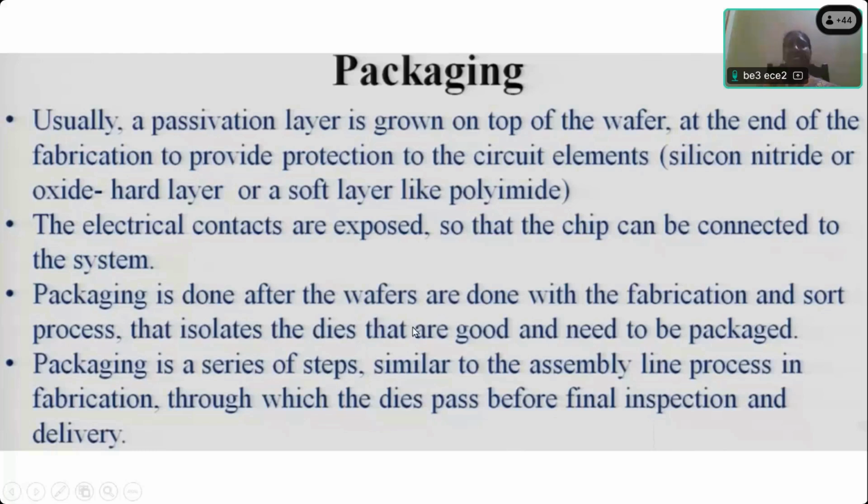And for bad dies, the profile also, profile means why it has gone bad. All those statistics should be maintained so that it can be sent again for fabrication. Any minute defects can be rectified, and it can be made a good die again. If more defects are there, we have to throw it out. In one single wafer, small squares are there, and we will cut each square separately after deciding which is a good die and which is a bad die.